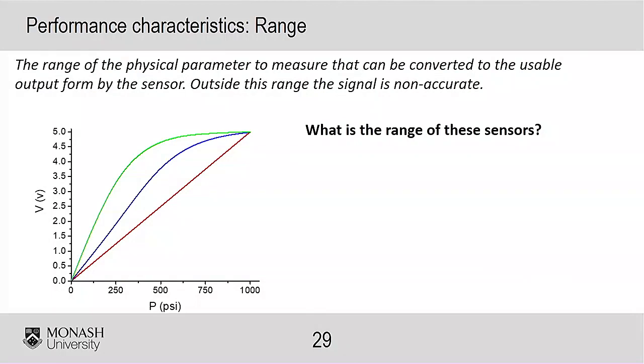So some examples of this include some flow sensors that I work with. Low flow rates are not within the specified range because they have an error of about 10%. Flow rates between, say, 2 to 10 litres per minute are quite good. They're calibrated nicely and only have about a 2% or 3% error in that range. And then obviously at upper limits, you then get more error.